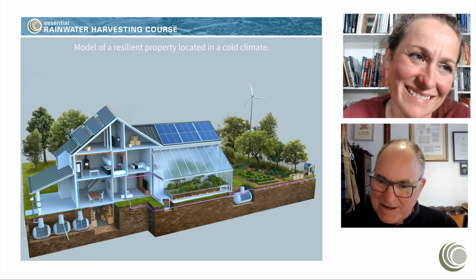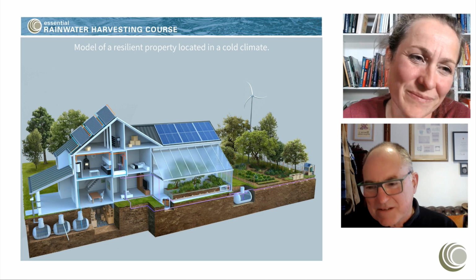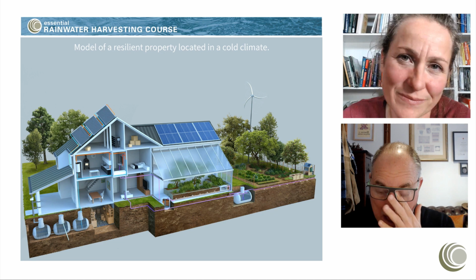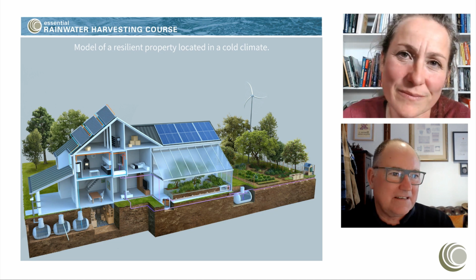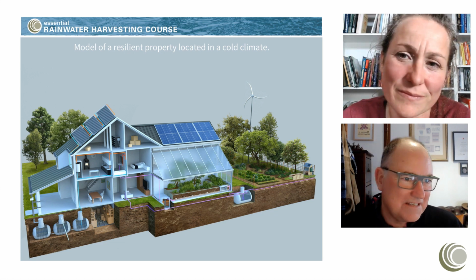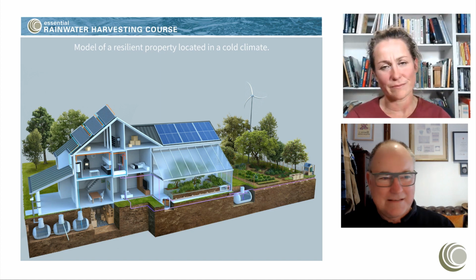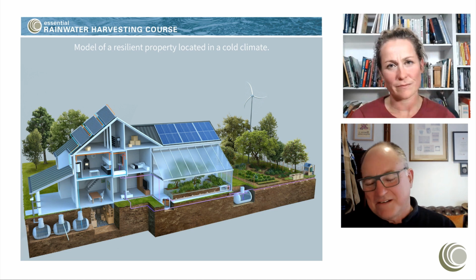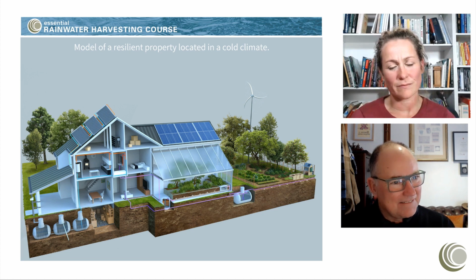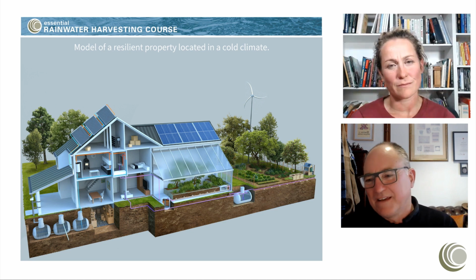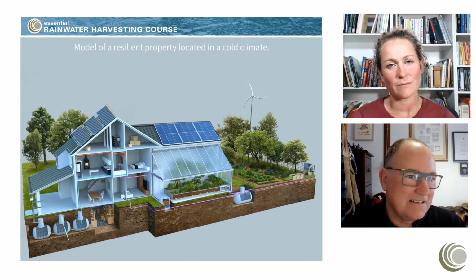But there are also really interesting interactions between water and energy systems, which some of our researchers discovered. The common rhetoric in Australia is if you use a rainwater harvesting system that might need a pump to supply, that means your energy use would be greater in your household. What we actually found is the opposite. The energy use reduced considerably because most of your appliances in your house actually need to operate at quite low flow rates and quite low pressures.